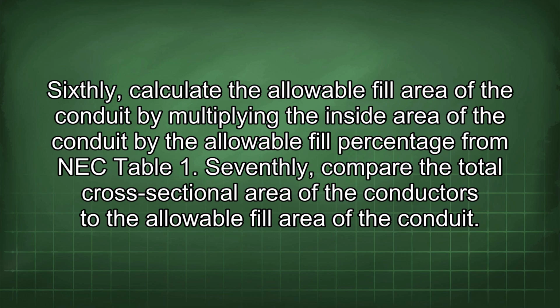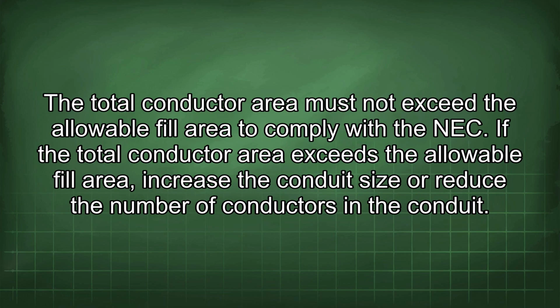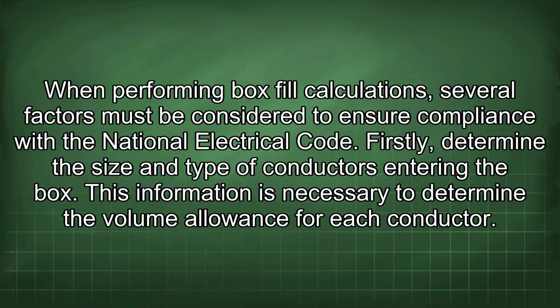Seventhly, compare the total cross-sectional area of the conductors to the allowable fill area of the conduit. The total conductor area must not exceed the allowable fill area to comply with the NEC. If the total conductor area exceeds the allowable fill area, increase the conduit size or reduce the number of conductors in the conduit. When performing box fill calculations, several factors must be considered to ensure compliance with the National Electrical